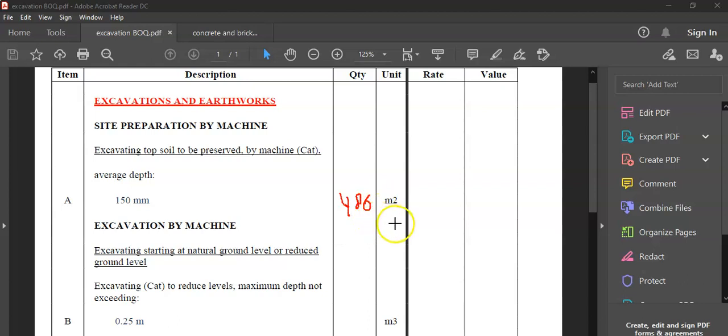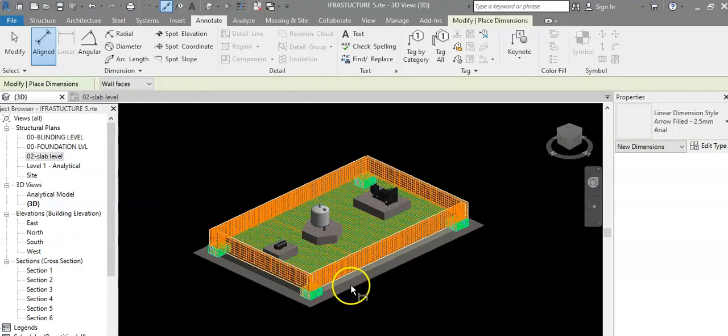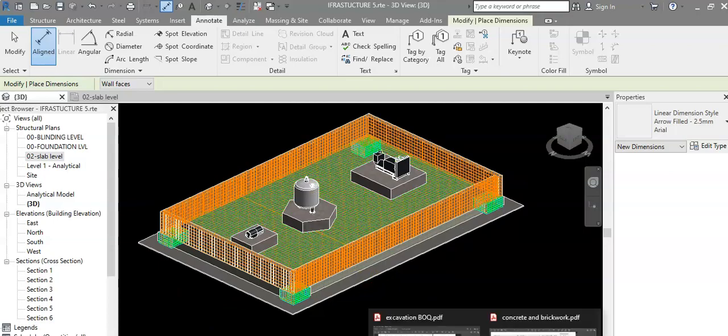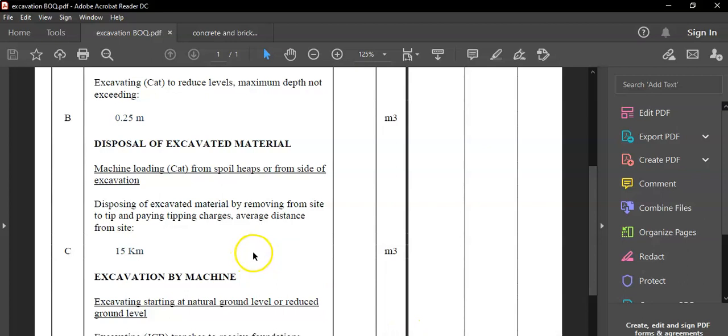The measurement in cubic meters will be quite useful to pass on to the foreman of works and the management, to supply the site with the right plant. If it is a large scale project, we will know that we need bigger machines and bigger transport dumpers to transport the topsoil to the allocated area. That's the reason for working out the volume, for us to know what sort of plant, machines, and resources we need to deal with the magnitude of the excavation and the disposal of this material. In the next tutorial, we will go more in depth with regard to the excavation and disposal of earthwork material.